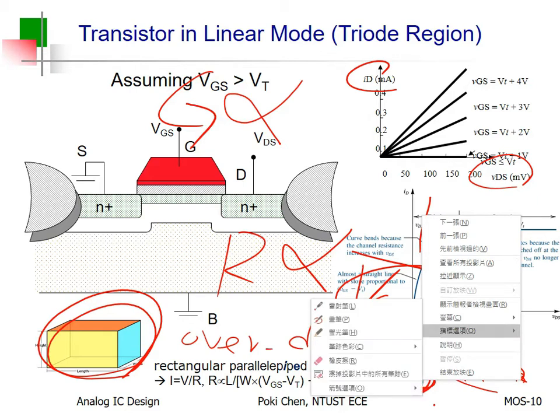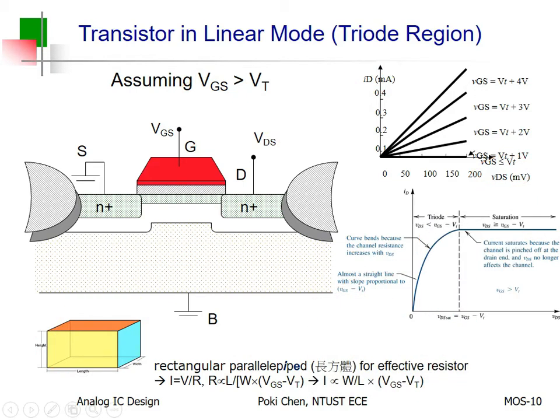Anyway, allow me to explain this for you. If your VGS equals VT, zero depth here, no conductivity, in theory. And then you increase it 1 volt higher, 2 volts higher, 3 volts higher, wow. The conductivity is proportionally increased. The more VG exceeds VTH, the better your conductivity. And what is the conductivity?